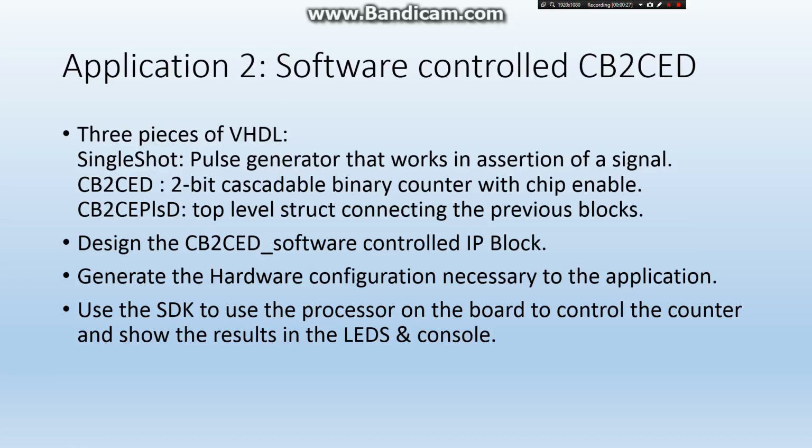the single shot, which is a pulse generator that works on insertion of a signal, and the CB2CED, which is the 2-bit cascadable binary counter with chip enable, and the CB2CE pulse D, which is the top level structure that connects the 2 previous blocks. We're going to design this IP block using Vivado, and then we're going to generate the hardware configuration necessary for this application, and then we're going to use the SDK to program our board.